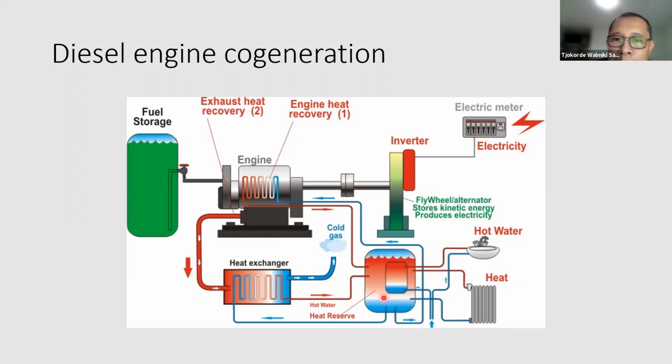Okay, and the water flows by natural convection through this heat exchanger, and because of the gradually increasing temperature the water will flow that way. Okay, because it's lighter. Okay, the density decreases as the water warms up. Okay, then in this tank we can siphon off, we can draw off warm water or hot water from the top of the tank. Okay, so because of the density difference in the tank, the hot water will float on top of cold water. So we siphon off hot water from the top of the tank.